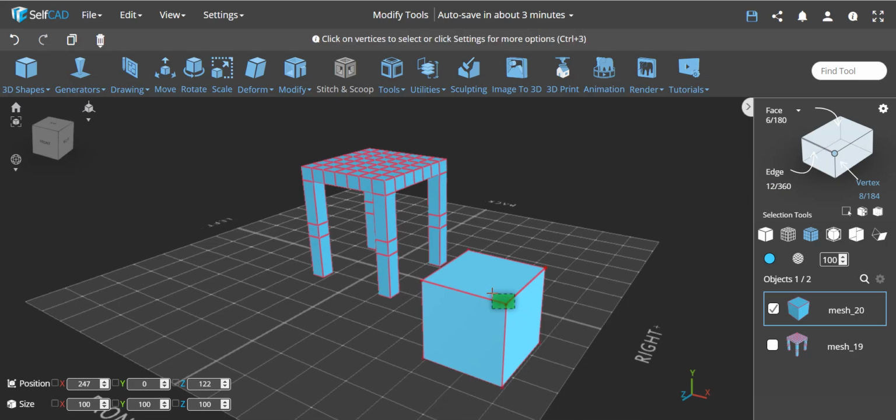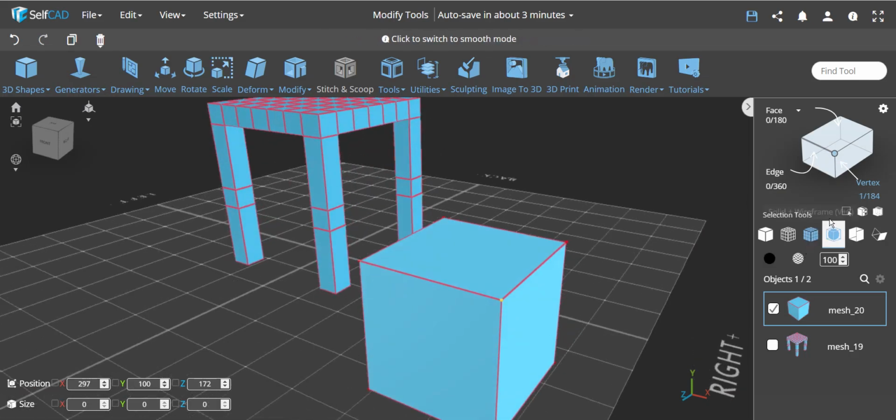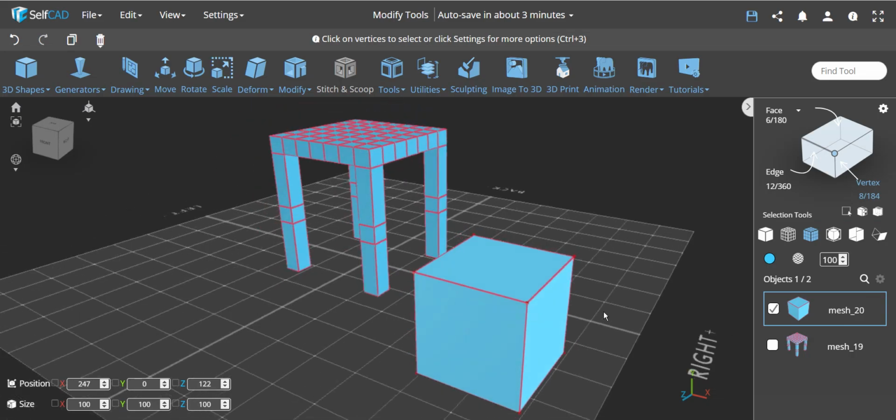If I select a single vertex over here, you see, I have only 1 vertex. And the reason here is because this vertex is repeated. It's used by this edge, by this edge, by this edge. It's used 3 times, the same vertex. If I'm going to duplicate this vertex, like each edge will have their own vertex, this would be considered also a non-manifold object, and in technical terms this is called exploded geometry.